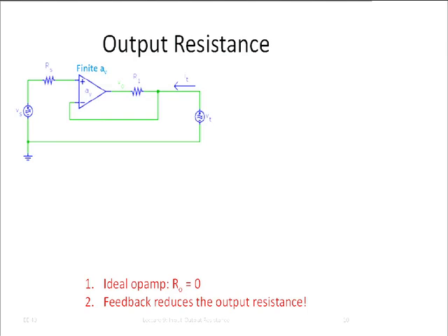Also, something that somebody asked in the office hour, and I would like to say here again very clearly: if the gain of the operational amplifier is finite, then the two voltages at its input are not zero. It's only when the gain is infinite that this voltage here is zero, but only if we have negative feedback, and secondly, the operational amplifier is ideal, including it having infinite gain.